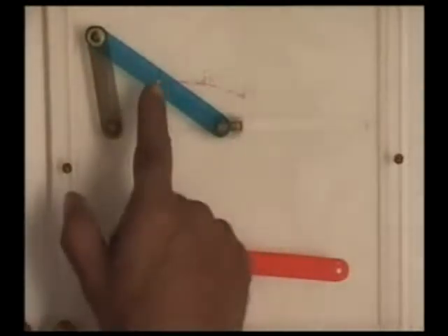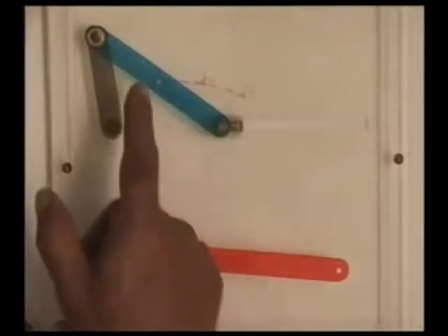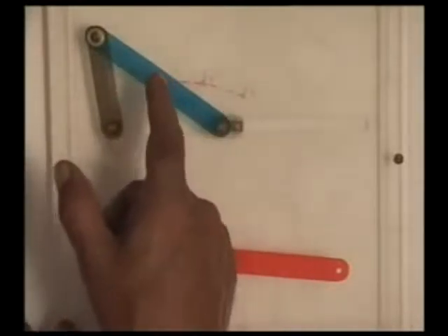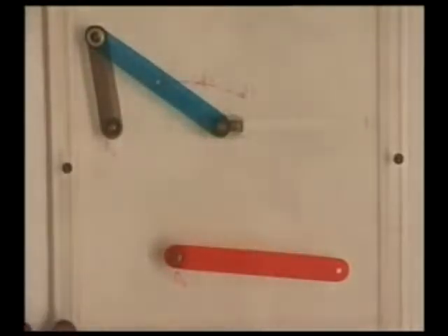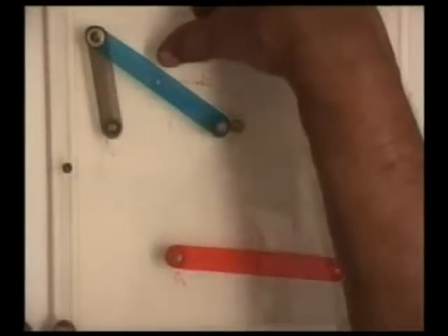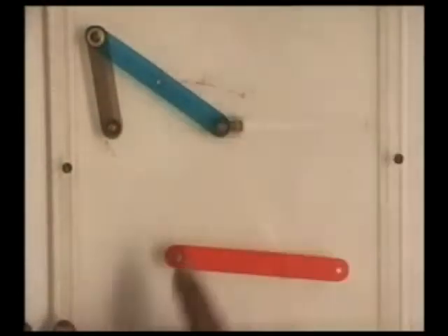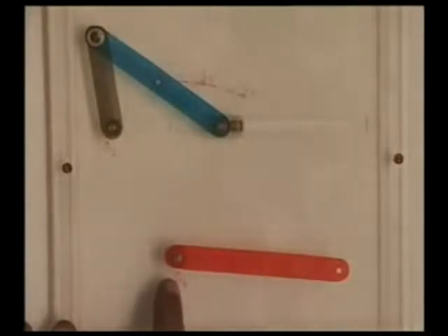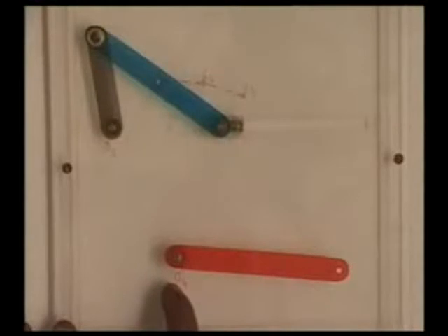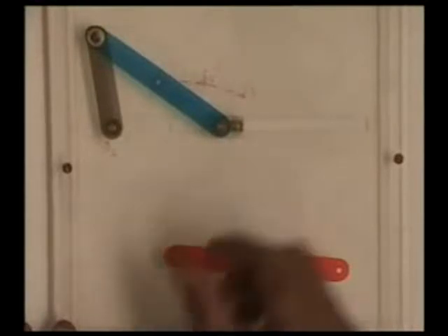So we mark this midpoint of the connecting rod corresponding to the three specified configurations as C1, C2, and C3. The center of the circle passing through these 3 points C1, C2 and C3 is here. So we make that our O4 for the required 4R linkage.